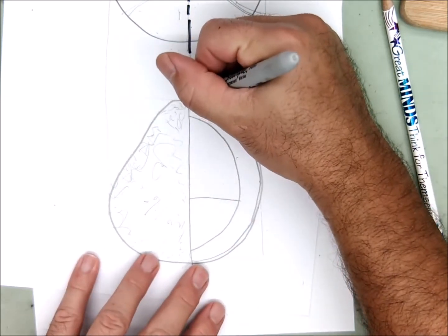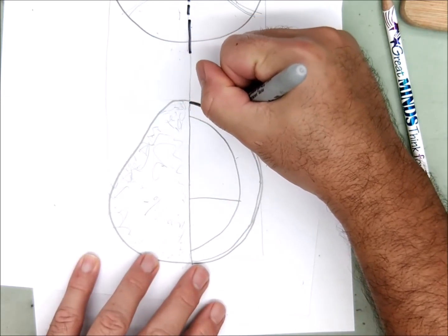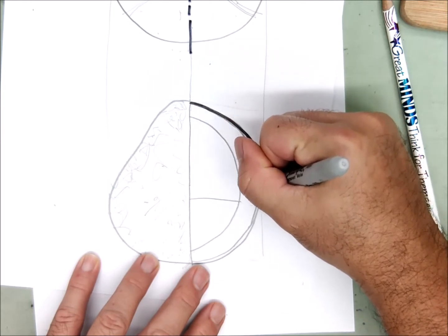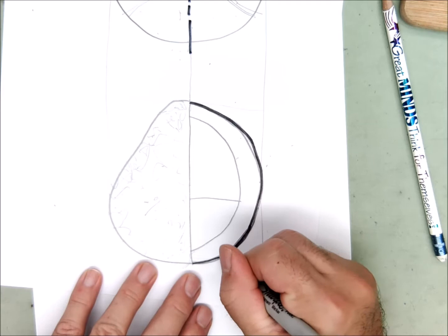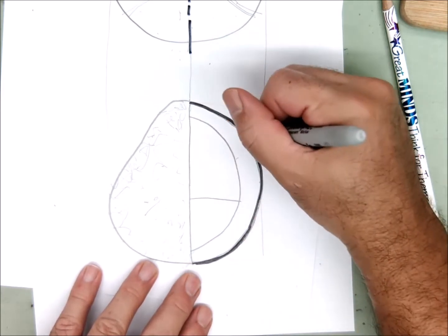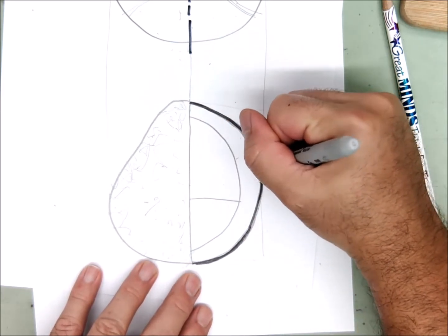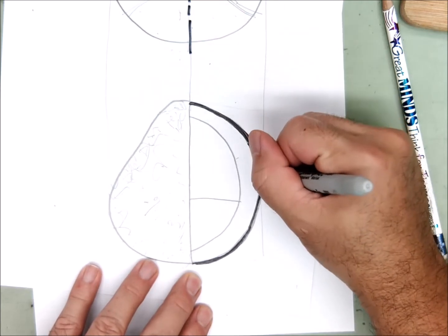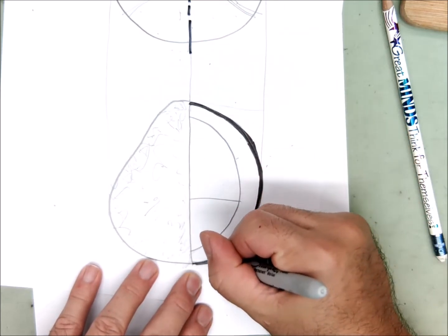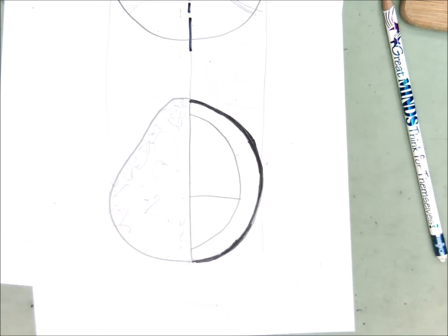Generally, things that are very thin, like a piece of sheet metal, or in this case, the husk around the coconut, they do not get sectioned. They're not thick enough to draw section lines in. So they're just drawn with a real thick, heavy line. And people will know that that's some thin, solid material.